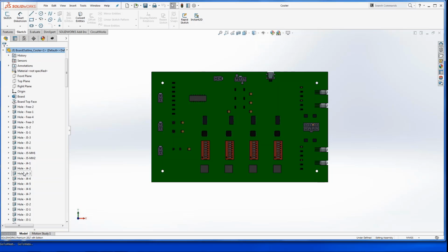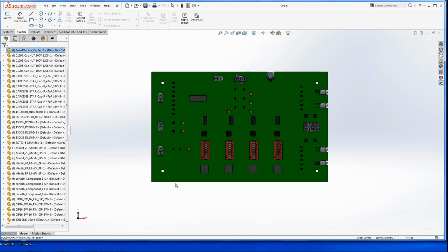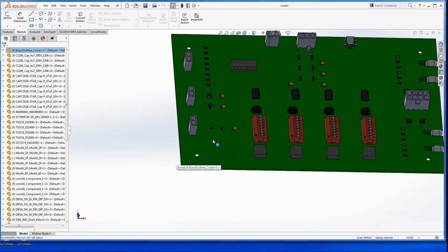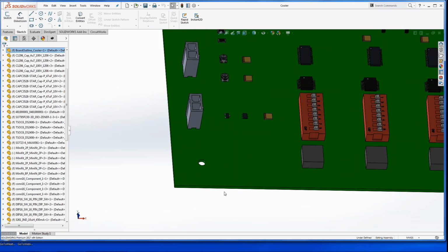And that makes sense from a mechanical perspective, also from an electronic perspective, because I want to move the models in SOLIDWORKS. I'm actually moving the components, but the footprints won't update until we go back to SOLIDWORKS PCB or Altium. The only thing we will do in SOLIDWORKS is modify the location of the models. We can modify the locations of mounting holes. I can modify board outline information, and all of that will be automatically updated to the PCB in real time.